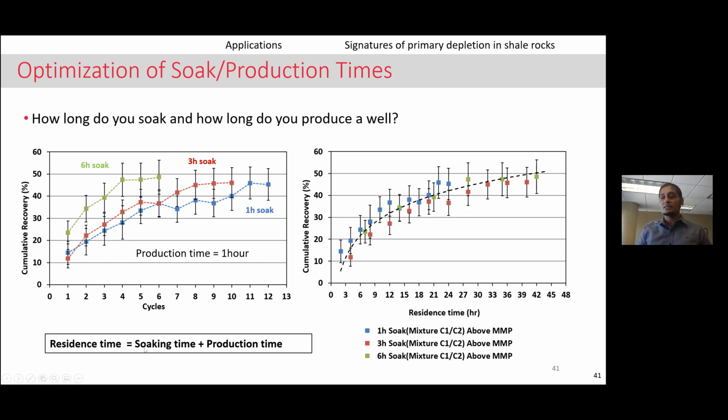What really matters is the soaking and the production time. And what we see is that if you are looking at cumulative recovery as a function of the number of cycles, of course, if you give it a 6-hour soak time experimentally, you would be recovering more oil, and you would think that, hey, we should give it a much larger soak time or expose the rock to the solvent for an extended period of time.